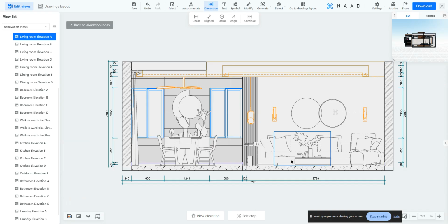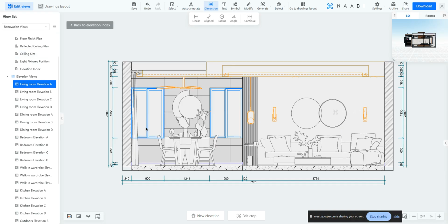So this is how you should be able to generate a wall elevation. Remember, this wall elevation will greatly be helpful in your wall panel design and in your ceiling section design as well. And if you are having any wall panel in your walls here, if you want to see a section of it, no worries. In your floor plan or in your ceiling plan itself, you can precisely see that cut part, where that wall panel is being cut.